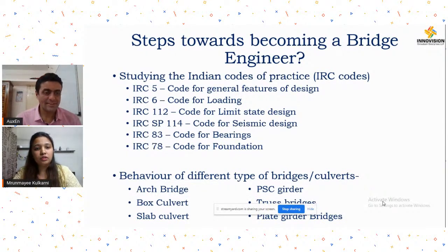Then IRC 112, this code gives you the guidelines for limit state design of the structure. Earlier, bridges were designed by working stress methods. In 2011, this new code came, and the revision has also come in 2020. In 2011, Indian standards switched from WSM to LSM. So this code is for those particular guidelines.